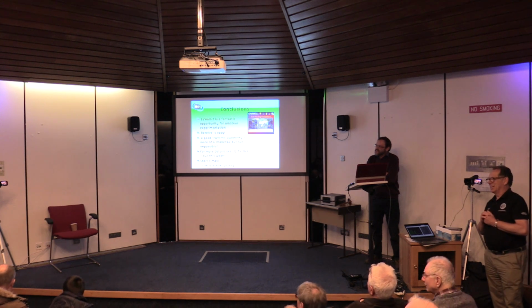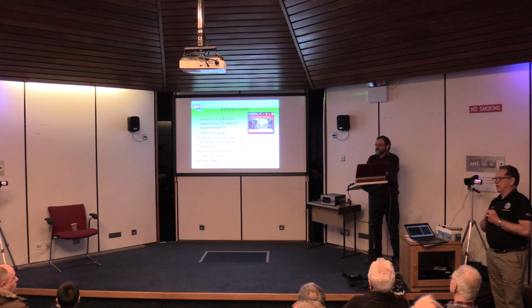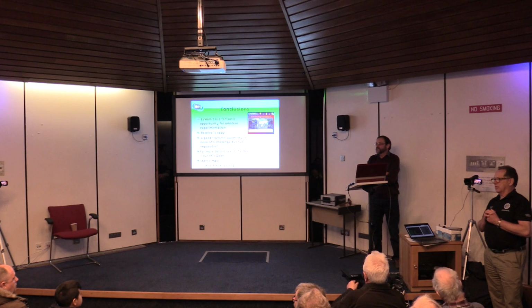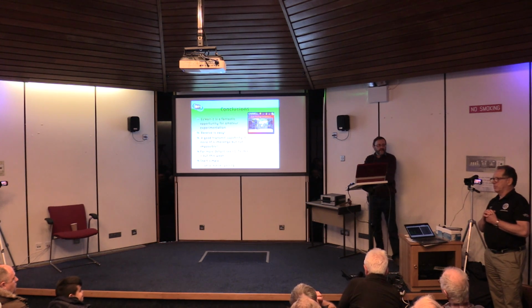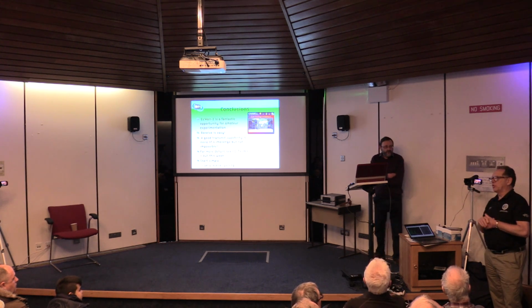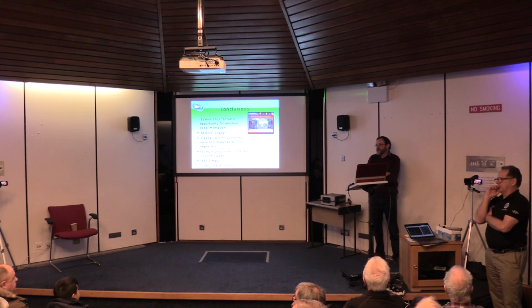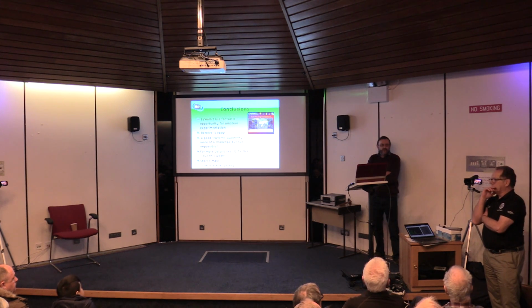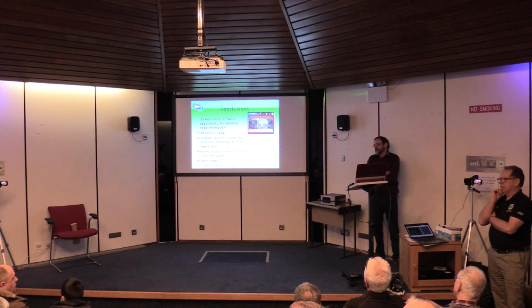Is the narrowband transponder a completely separate entity from the wideband transponder? Yes. And they've got separate PAs as well? Yes. Separate TWTs? Yes. It's the same receiver though, isn't it? It's the same receiver, split, and the same receive horn. Right, and they are redundant, so there is a redundant TWT for each of the two parts? We're not 100% sure. Or you sacrifice the wideband one for the narrowband one?